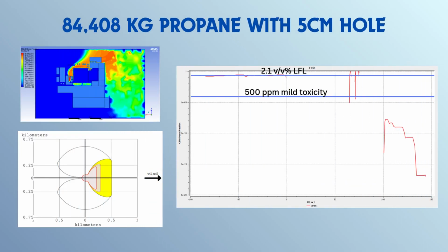With this analysis, important information can be gathered. It can be noticed at what radius from the source a leak would be intense enough to be over the toxicity threshold and lower flammability level. It can be observed if the neighboring areas are affected by toxic hazards or fire hazard at different leakage amounts and hole sizes.